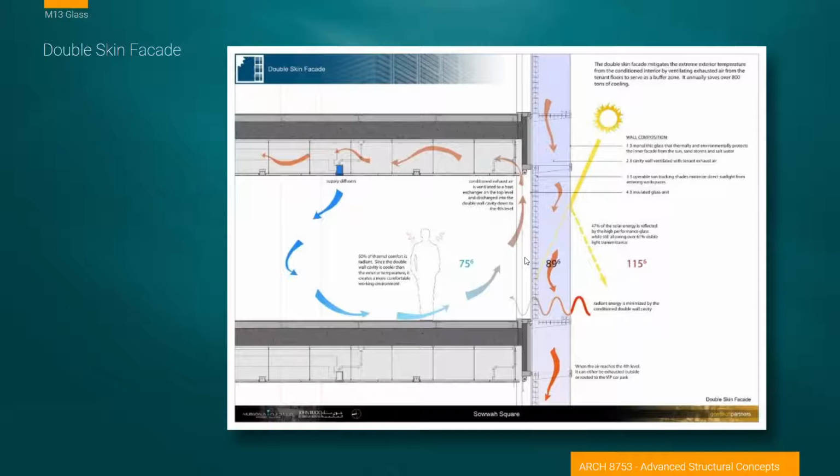The problem here is not that these aren't good ideas. The problem is the devil in the detail, so to speak. Now the facade becomes a really huge, active, critical component in the performance of the interior conditioned space. And because a lot of people like to have control over what happens at this facade level, the ability to open windows and close windows and control those things, we have many inherent conflicts between what the user desires for thermal comfort at the outside of the envelope and how the envelope needs to perform to create the right conditions inside of the complete building envelope.